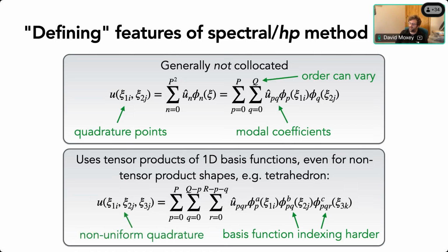The other thing that we tend to do is that in using the Duffy transformation to collapse onto the reference element, this introduces a singularity where you've collapsed it. And that singularity is removable, and you can show it doesn't affect your expansion order. But from an implementation perspective, it's a bit of a pain because it requires some special treatment.